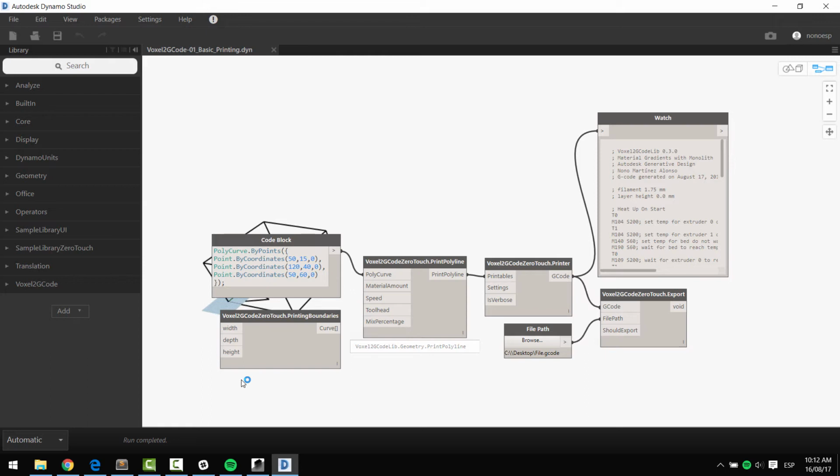So you could apply that same thing to any VREP model? Yeah, any VREP. If you make your own slicing process, or your own operation to generate the lines, so the paths, you generate the paths, and then when you have those lines, you input them and attach different properties. So for example, things I tried, not even using voxel models, you could have a surface, you can slice it, and then each of those curves you rebuild into polylines, and once you have that, you can get the polyline, map the velocity or the amount of material to the z coordinate, so you can have a model that goes printing faster as it goes up, or things like this.